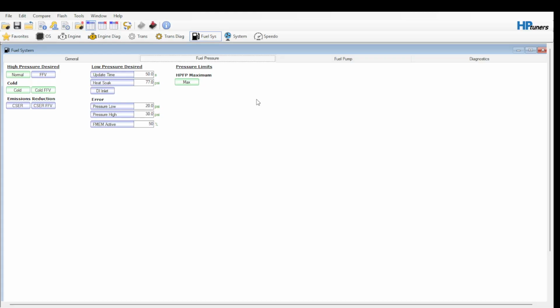The F-150s that don't have port injection have a problem because they don't have port injection. That's the reason the new ones have it, right? Carbon buildup on the valves. So not a good thing. It means your valves can't do the closing thing. The whole thing they're designed to do is close and open. And that's not good. You want your valves to be closey and not loosey because of the carbon buildup. Carbon's not just bad in the atmosphere, it turns out. And when you run E85 or an ethanol methanol water mix over those valves, it's going to clean them up rather well. But the problem is that that's a tuning